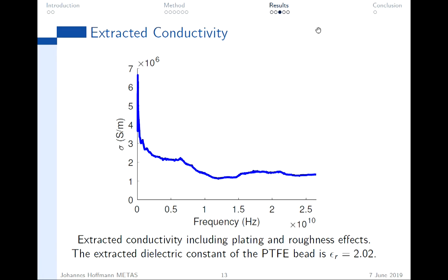This is basically copper beryllium gold plated. Most of you would expect much higher conductivities, but this is not the case due to there's a nickel layer for adhesion, which is making things worse, and as well surface roughness, and so you get this kind of behavior here.